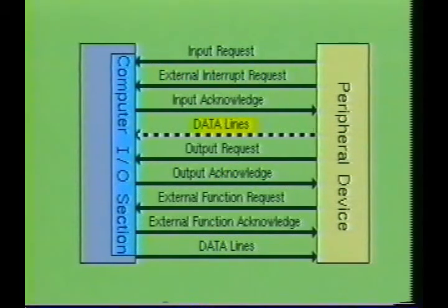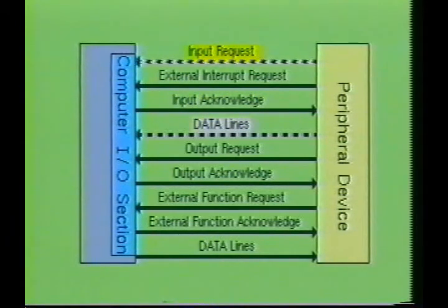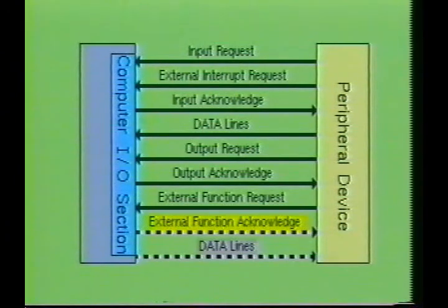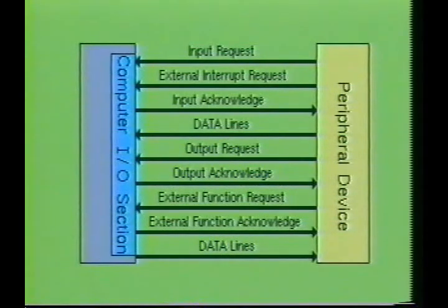As you have seen, the processor and peripheral devices are able to communicate through a series of control signals placed on the various control lines. After the requests are honored, each device will perform its function. However, these peripheral devices send their messages to the processor at irregular intervals with requests for service. It is typical for more than one peripheral device to send a request for service at the same time. Therefore, a circuit is required to determine which device should have priority and be serviced first.